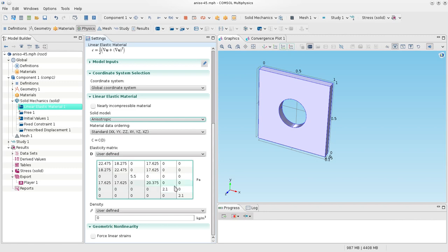All right, and notice that the values are slightly different now. They are not the same, unlike the orthotropic case, because of the rotation. And likewise here I've got off diagonal terms within the normal part. So again, that has to do with rotation. More importantly, the terms that have to do with normal shear and shear normal coupling, they're not zero anymore, which means there will be some coupling.